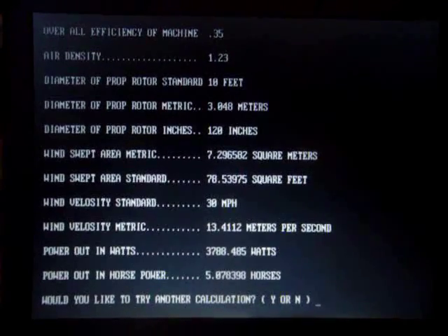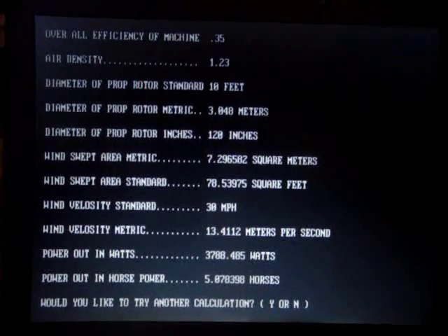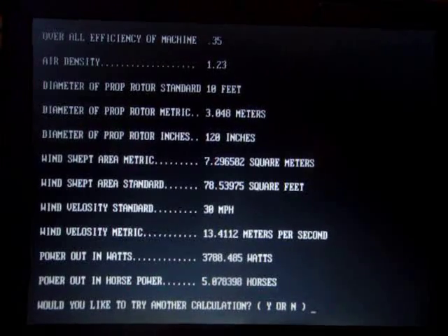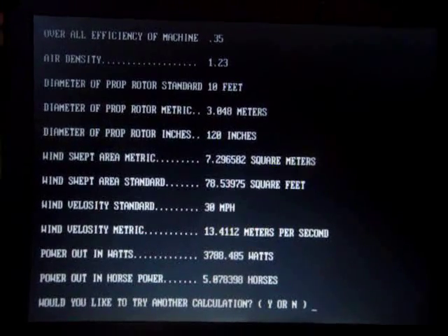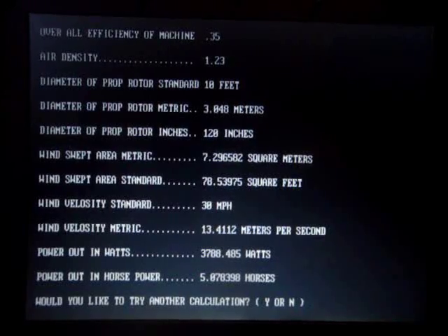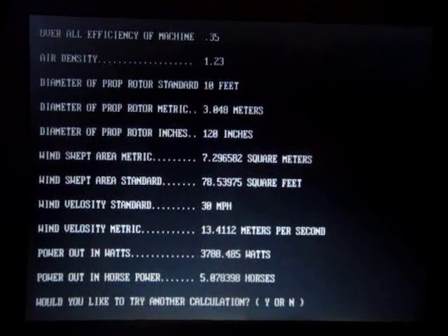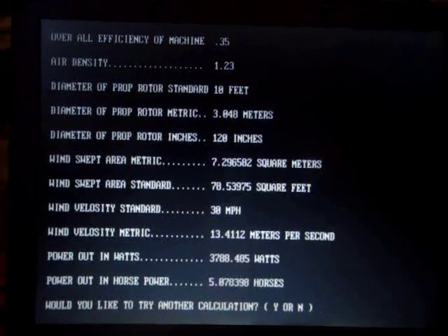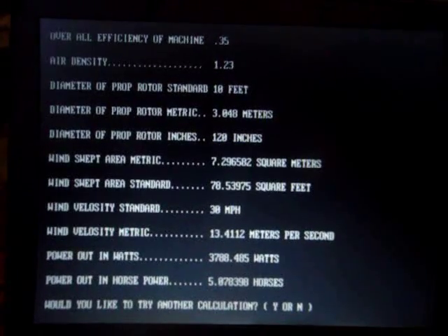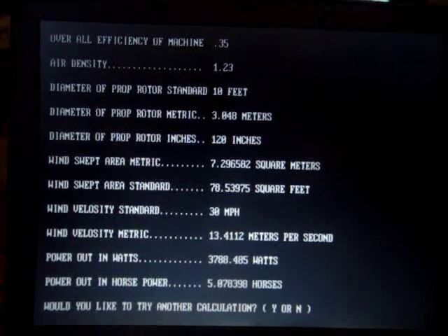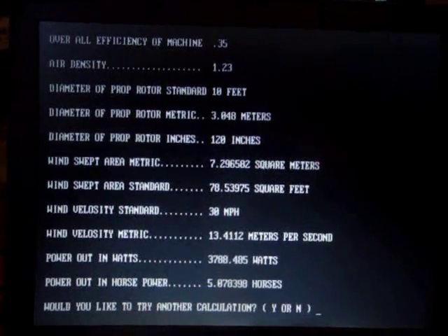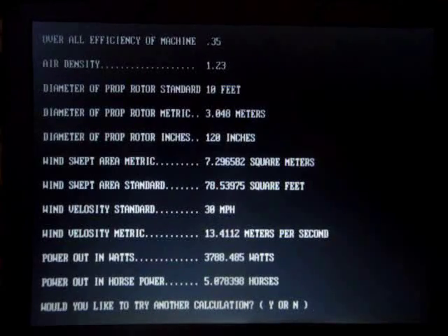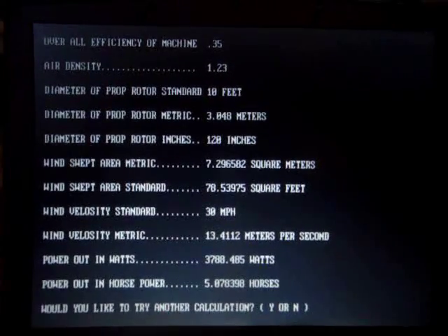These are optimum results, the power available in the wind per size of prop. You can only get these out if your prop is matched to your alternator. If your prop is not matched to your alternator, if it's too big, it's going to turn too slow, and you're not going to get the voltage until the wind gets up there. And then when it gets up there, you're not that much higher than your battery voltage, so therefore you're not trickling any amps into it hardly.